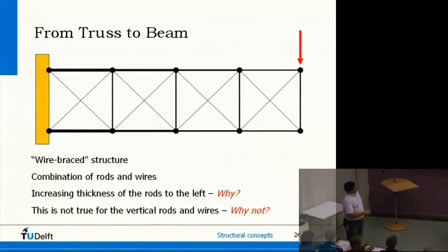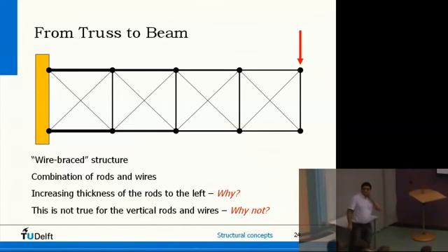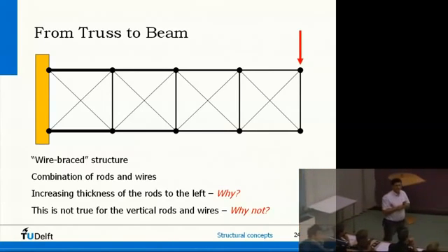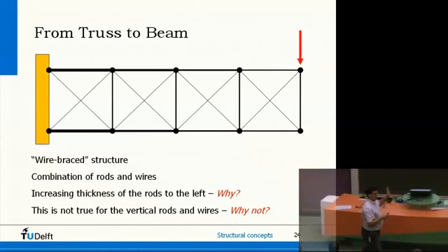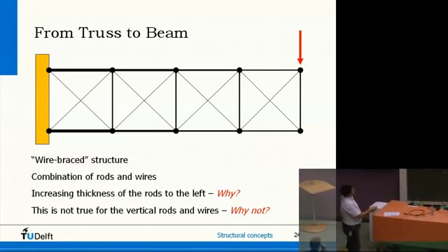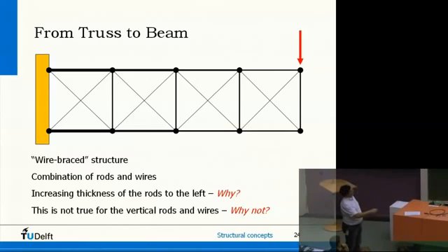And what's striking is that the bar at the top side is increasing in cross section from right to left, both sides. You may ask, why is that? The moment becomes larger when you go from right to left. So if the wall was placed here, I only have a very small, tiny bending moment in my beam, with a compression at this side and a tension at that side. Now I do have a very large bending moment because it's the force times the length of this arm, and it has to be transferred to the wall via these horizontal lines.